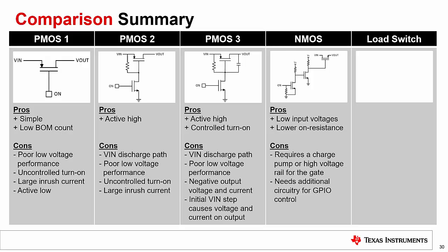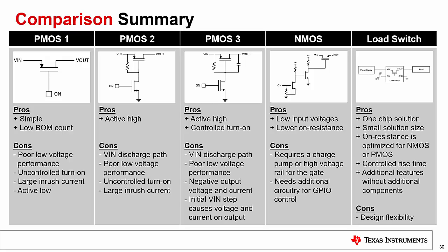The NMOS solutions have the same AC considerations as the PMOS solutions and offer better performance with low input voltages. These solutions can be more complicated, however, due to the circuitry needed to apply a high voltage to the gate of the NMOS. The load switch offers a one-chip solution with controlled rise time, a small solution size, optimized on-resistance, and several integrated features.